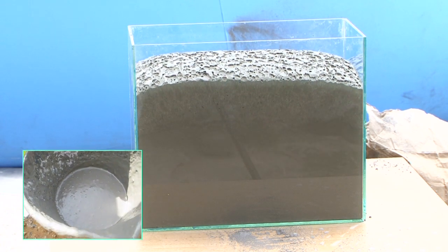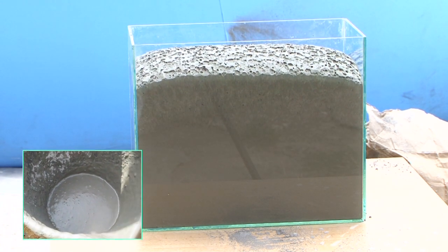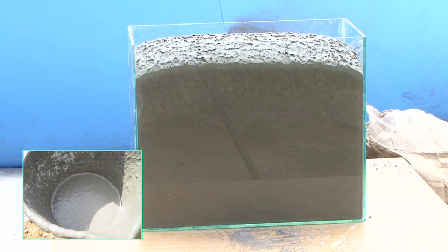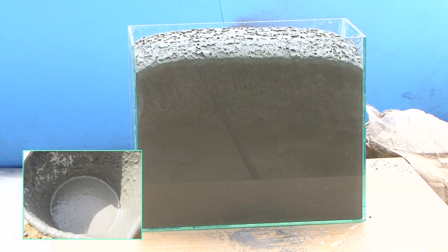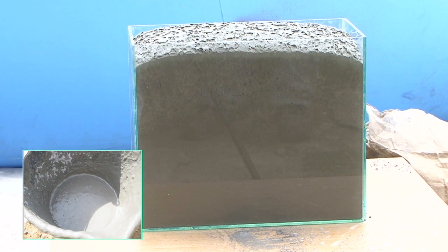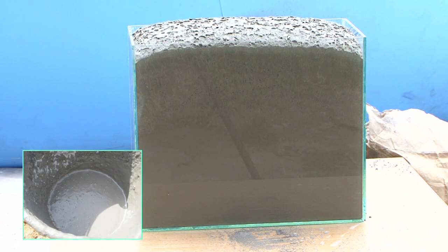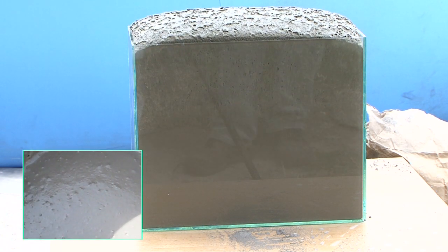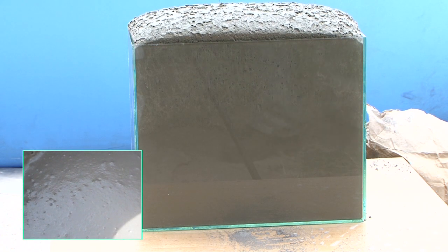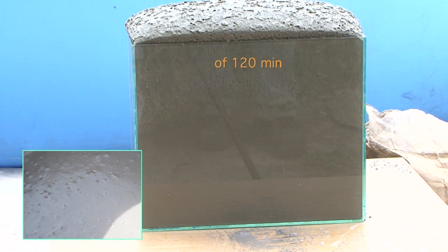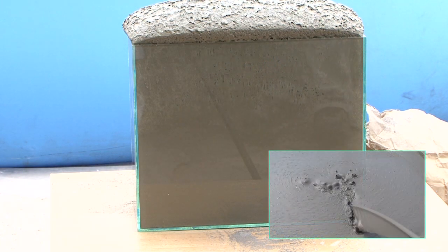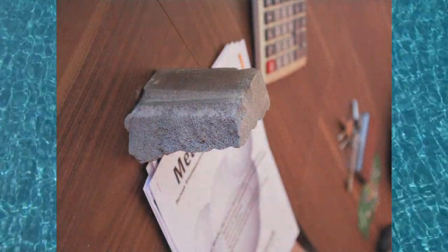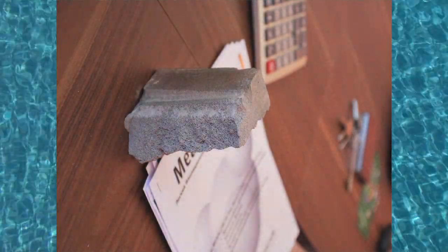The ratio of water to dry mixture for preparation of the suspension depends on the application and is determined by trial. As a rule, this ratio is in the range of 30 to 90 liters for each 100 kilogram dry mixture. The intense mixing of the CFC dry mixture with water leads to the preparation of the gas cellular concrete, which matures after it is poured, increasing its volume 2 to 4-fold and gets its initial hardness.